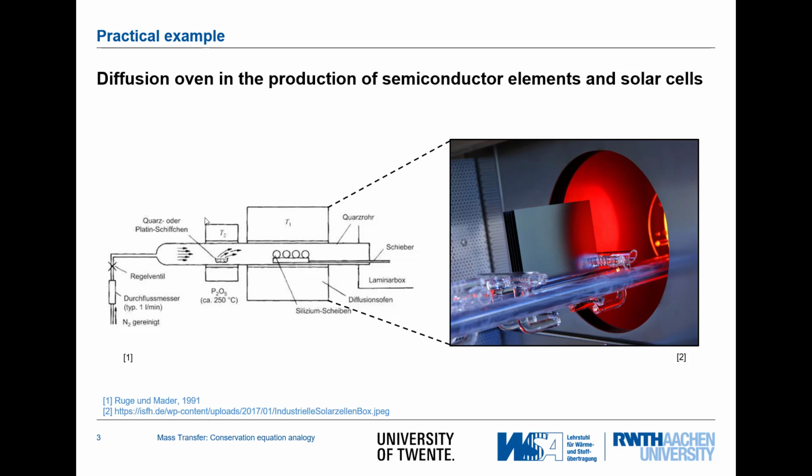The key part of it is that we have a kind of material that should be sedimented or that should diffuse onto the silicon wafers, and that we heat these two compartments in order to drive this material towards the location with this flow assistant driving, and then it will, due to the higher temperature, diffuse into the material, which is the aim: to bring the material towards those silicon wafers.